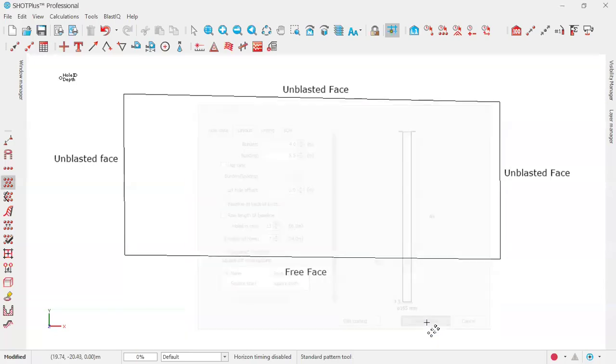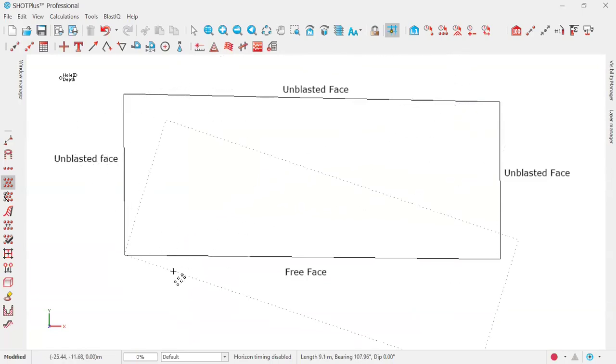Then you click on add pattern. After that, you see the pointer has changed. So you position it where you want the pattern to start. I want to position it here, so you left click there. When you left click, there will be a shape, and that shape is based on the values you entered for the parameters. This is the shape of the pattern that you get.